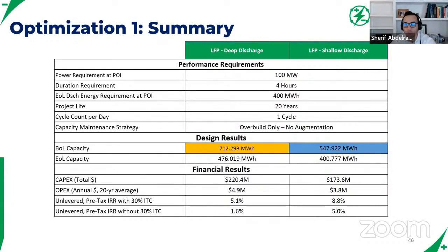And really for all battery systems, something to make sure you're aware of is that efficiency is not constant. When we say lithium round trip efficiency is 85%, that's a really general statement. It could be much worse if you're just keeping the battery there and not cycling it. So if you're interested in a comparison between two different technologies like lithium and flow, it's important to model both and see for your specific use case which one makes sense.